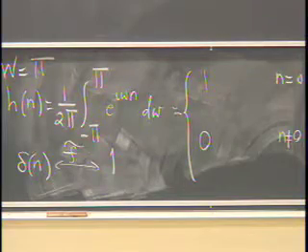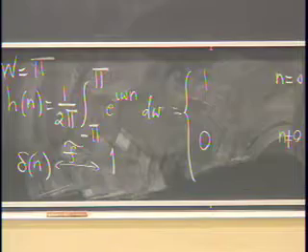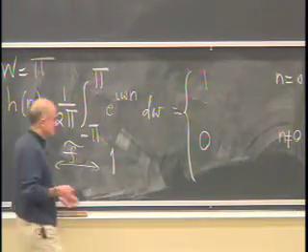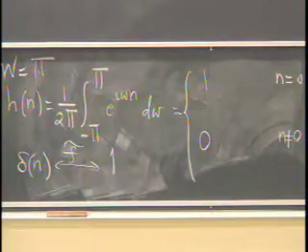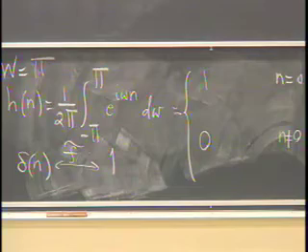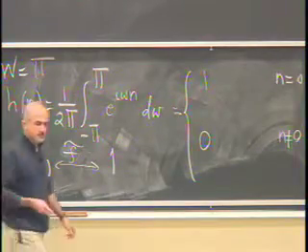The impulse in time gives you flat out occupying every frequency there is for a discrete time signal. And the narrower you make the frequency response, the wider this lobe becomes, just like you've seen before with a sinc.